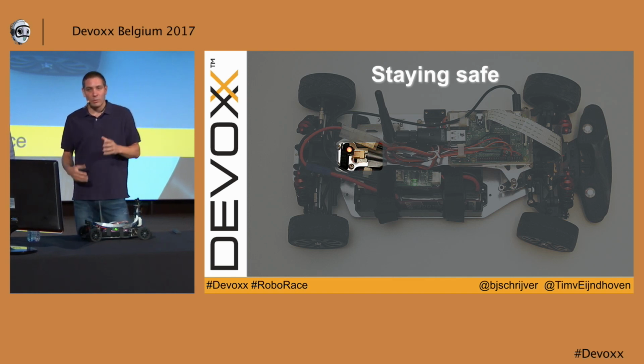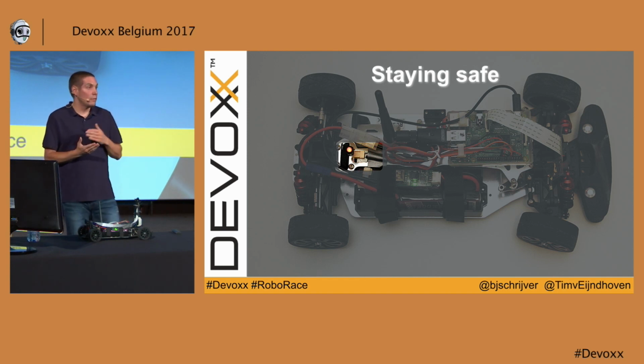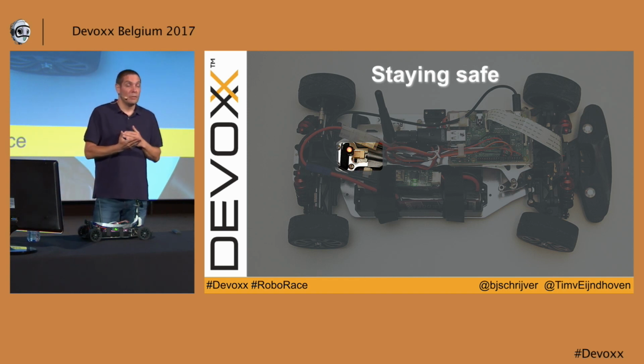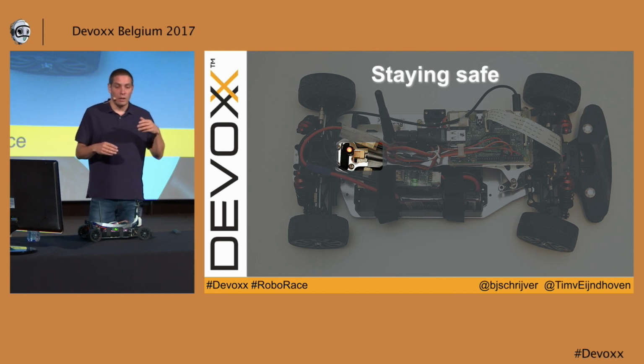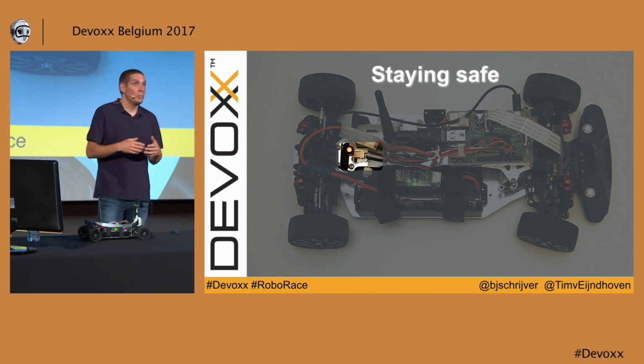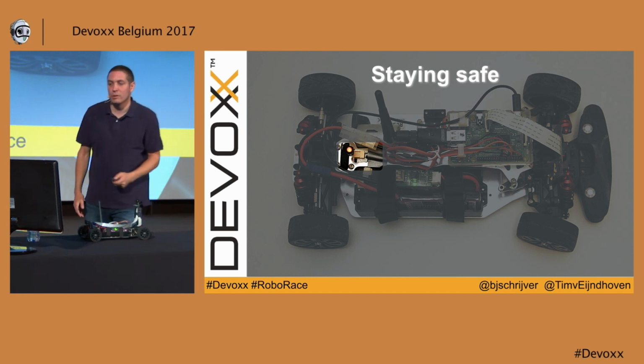a little. So we figured out that we need to work on some safety measures first. So what we're doing is the control server that's running on the laptop is sending a heartbeat signal every 100 milliseconds to the Pi. And if the Pi doesn't receive, I don't know, 2 or 3 of these signals, then we'll shut down just as a safety measure when the Wi-Fi connection is a bit spotty, or maybe the Wi-Fi connection drops, or the laptop shuts down. So safety, even in such a small situation, was fairly important for us.